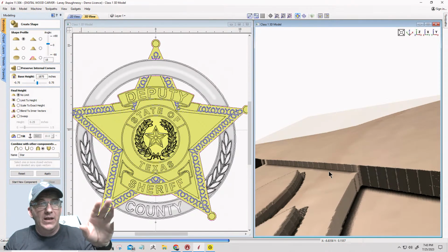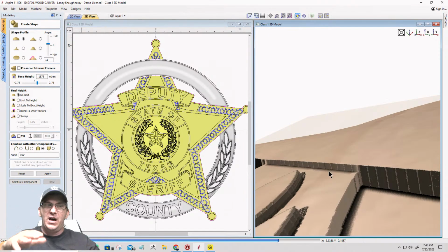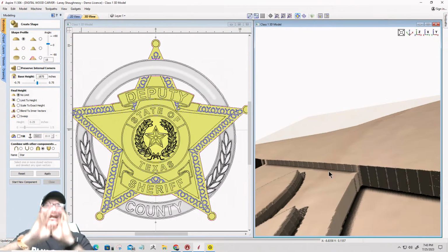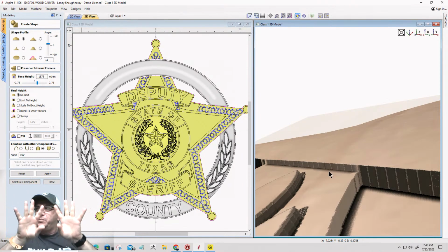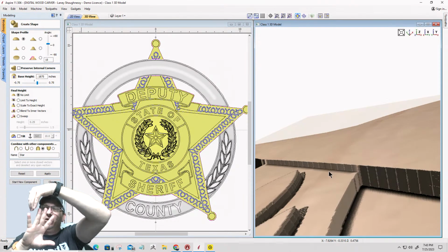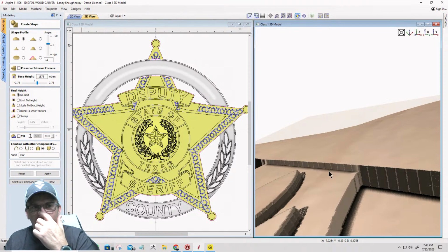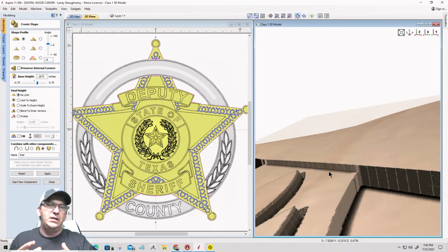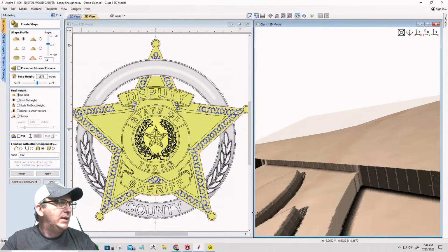fiber. Now, this isn't really that bad on the grand scale of things, but on some models, when it pushes up, it creates these little splinters of wood. And when those splinters of wood are sticking up, then your bit's trying to carve those splinters of wood. It's trying to carve those little bitty fibers, and it's not good. Not good with the model.